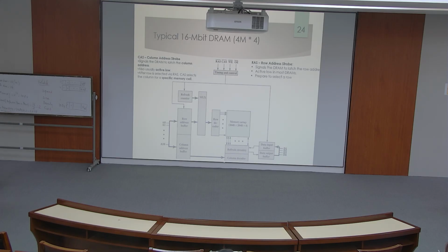We have address lines, as depicted by this picture. We have different address lines, A0 till A10, and we have the row address buffer and the column address buffer. So we have the row decoder as well as the multiplexer. We will learn about how the CPU selects one word out of these millions of words later on in this course. And you see, here we have a refresh circuit. This means it's a kind of DRAM that needs to be refreshed to retain the data.